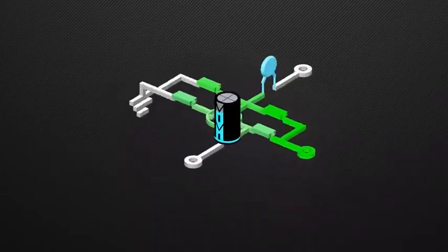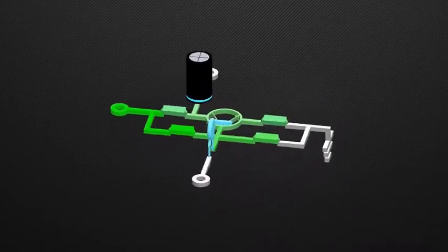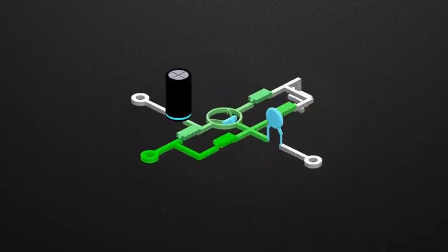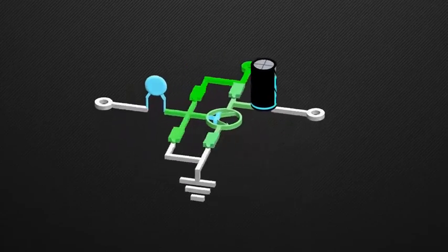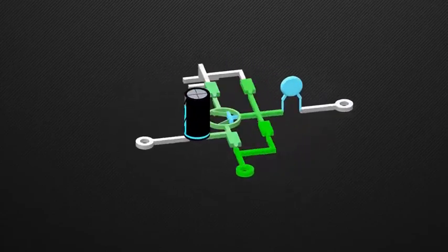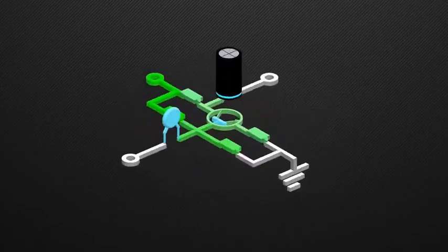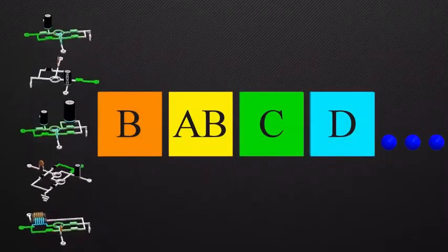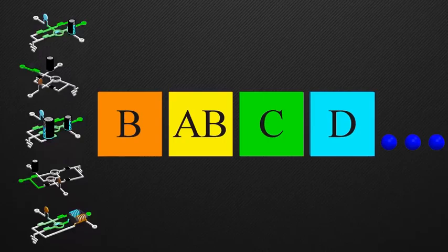A Class A amplifier can reproduce the full waveform, with very low distortions, but as the transistor is biased, it's always on. This and some other factors reduce its efficiency to less than 30%, which is very low. Now you know how a Class A amplifier works. In the upcoming videos, we will explore the remaining classes of amplifiers.